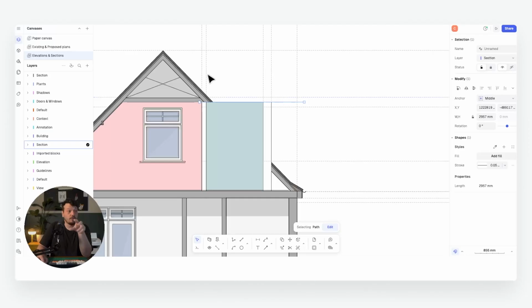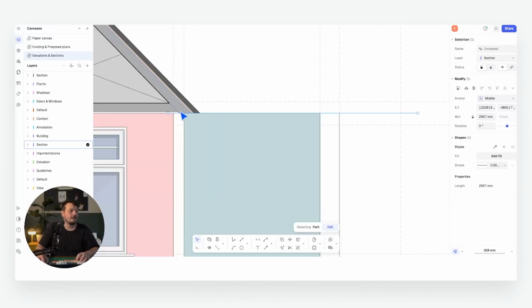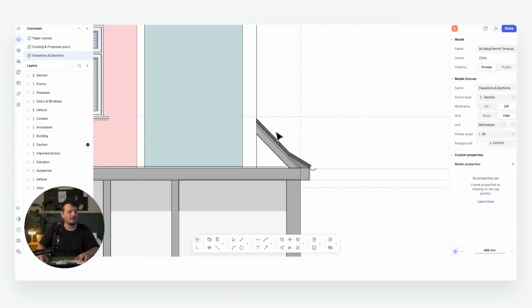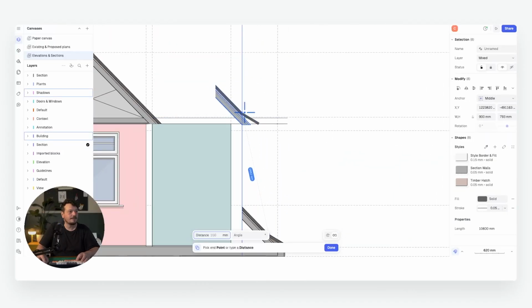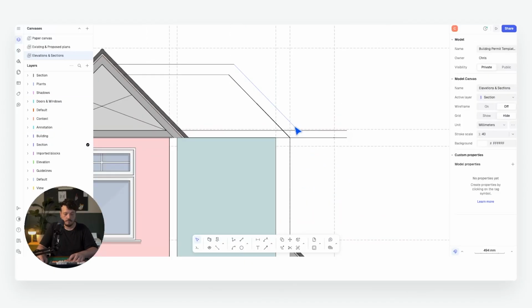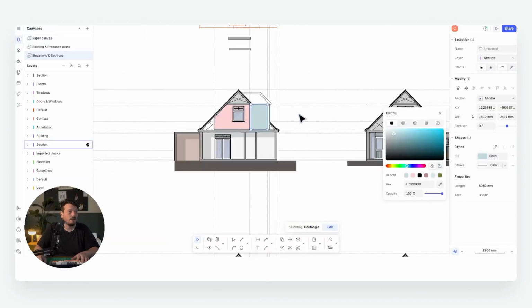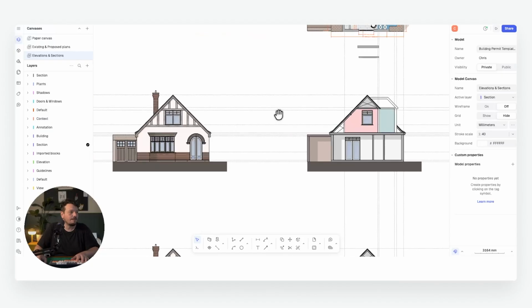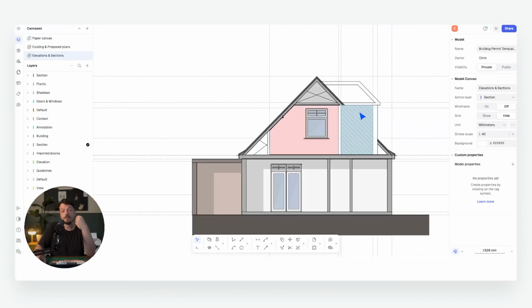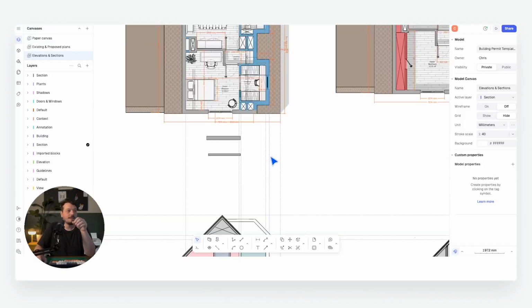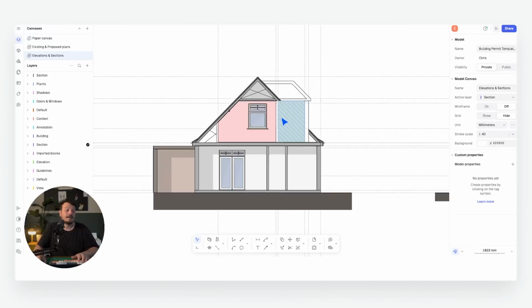This will then obviously have a roof, a pitch roof that sits comfortably with the external space, and ideally we want that to follow the same pitch as the existing. So with that very basic volume set, we can now think about how that impacts the elevation. And I just wanted to do that so I know that those spaces work, the head heights work, basically proving the plan makes sense, I suppose.